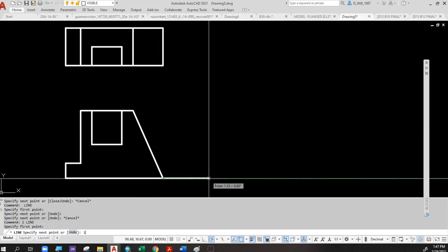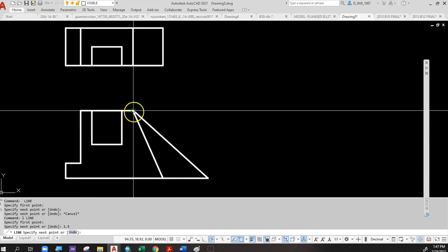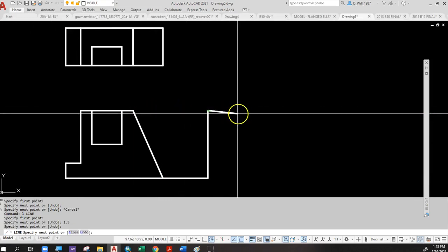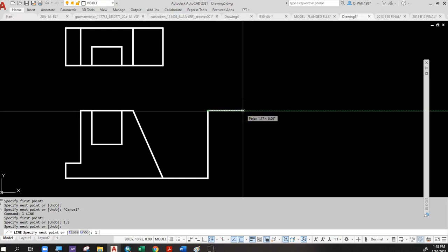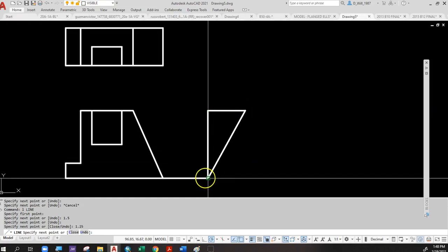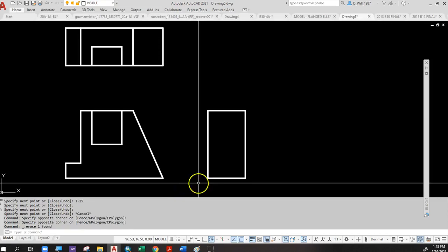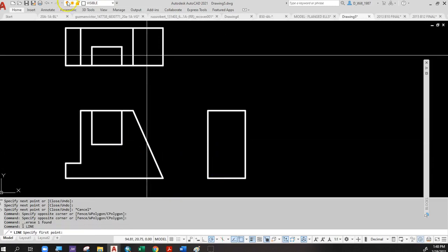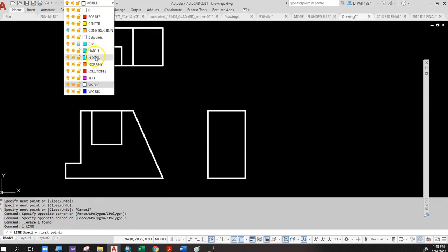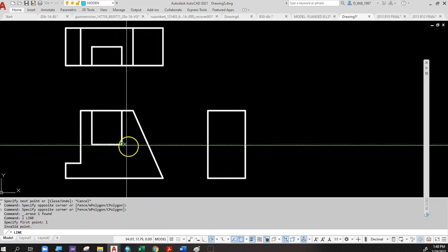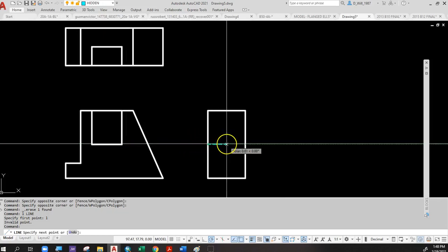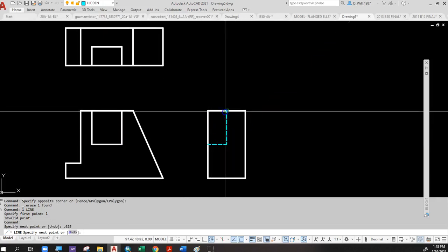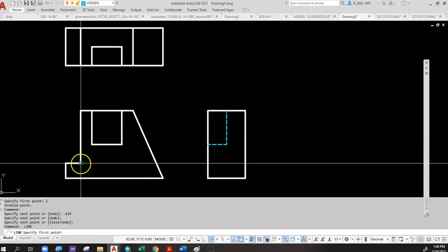So I'm going to go over here, 1.5 inches, and then we'll track. So you can see I used construction lines in my first attempt to do this. I'm using tracking in my second attempt. In the end, you get the same answer. So it really doesn't matter which way you do it. Okay, I guess maybe this is one less step, because now we don't have to go turn that layer off when we're done. You could look at it like that, I suppose. Track, track, track, and the tracking replaces a construction line. Point 65, and then up. And then this guy here, acquire the point and come over, bang, bang, bang, smash.